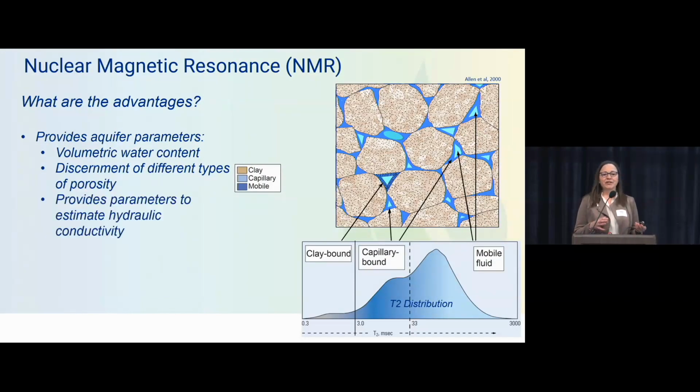Now, having that information, the distribution of pore sizes and also the total water content, allows us to calculate hydraulic conductivity using a variety of different models that are developed and some constants for that type of material.